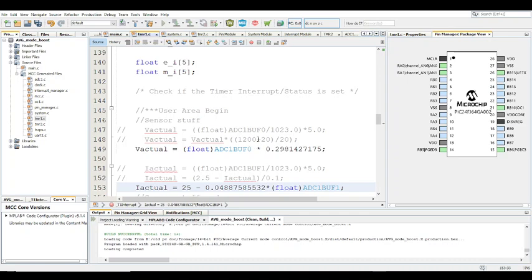The big resistor is 1.2 megaohms and the small resistor is 220 kilohms, which is quite small, but we're dealing with smaller voltages, so it's fine. You can make the resistance relatively small, but 20k is relatively small when you're talking about sensing, because you want your sensor to be high impedance so it does not affect your efficiency.